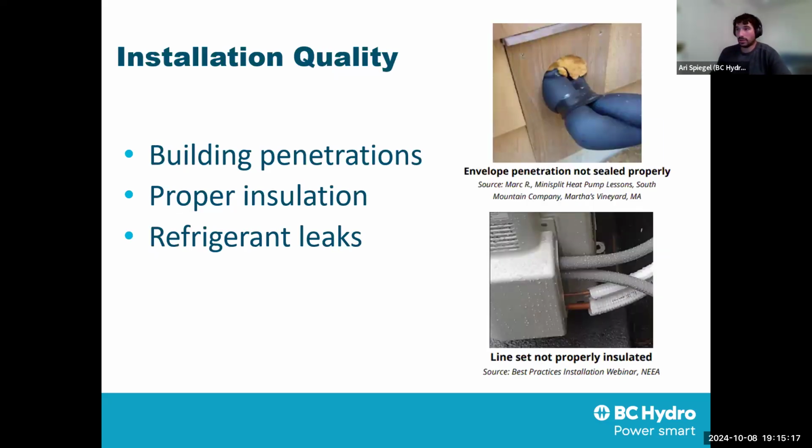And then, like any home renovation project, installation quality plays a huge role in this. However, I think with heat pumps, just because they're so sensitive in terms of that supply air temperature, any shoddy workmanship can stand out a lot more than, say, in conventional fuel systems where there's just so much heat that you may not notice a little bit of a draft or a little bit of leak. But when you're dealing with these low supply air temperatures, any sort of cold inrush you can really feel it. So things like building penetration.